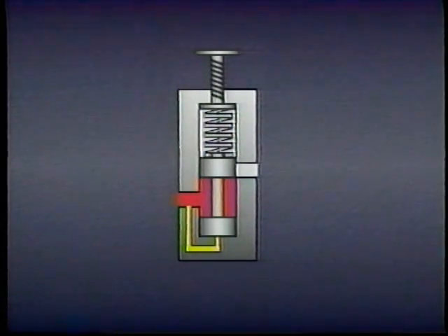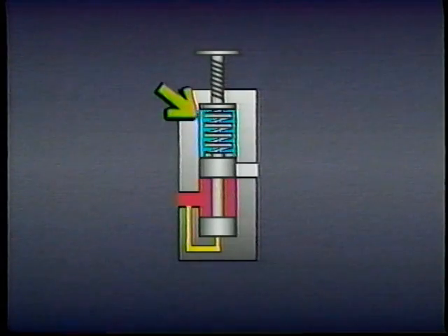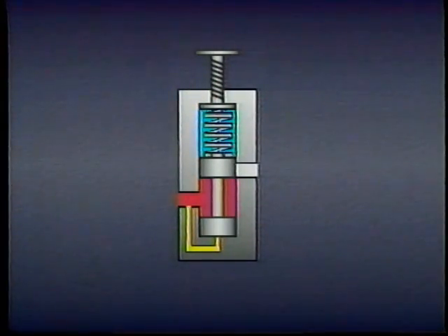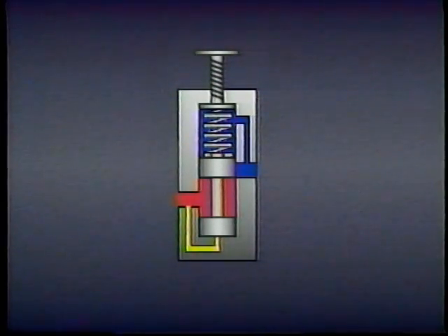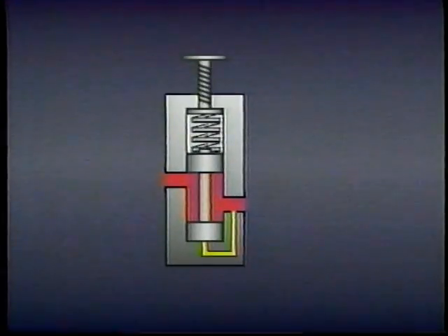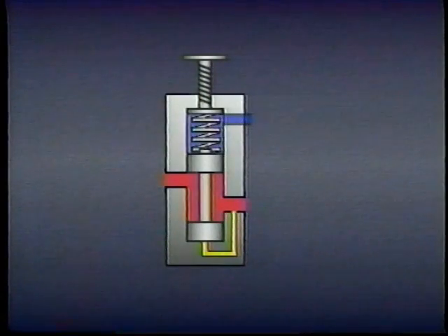All pressure control valves use some fluid for lubrication, but as a valve wears out over time, fluid leaks past the spool into the spring chamber. Excess fluid in the spring chamber will interfere with normal operation and must be drained. Many drains are internal. That means they empty into the secondary port. This works well for relief valves and other valves with secondary ports that return to tank at low pressure. However, the secondary ports on pressure-reducing valves and sequence valves contain fluid at working pressure. Trying to drain the spring chamber into the secondary port in this case would prevent the spool from shifting properly.